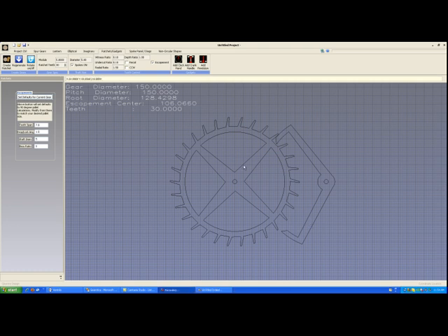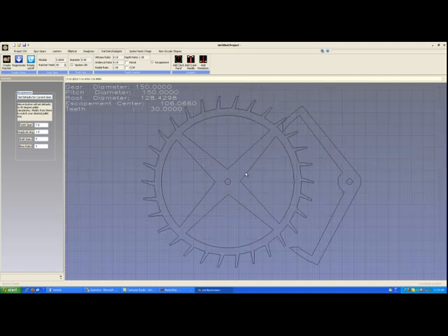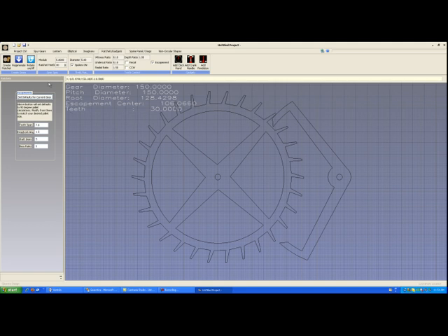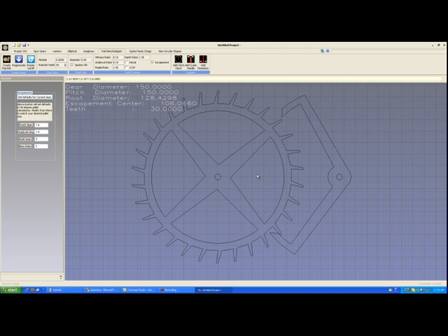So let's take a look at how an escapement works. The simulation mode on the escapement screen is purposely made very slow so that you can do a good validation of how your escapement is going to work. And if I turn on rotate, you're going to see that the pawl begins to move very slowly.